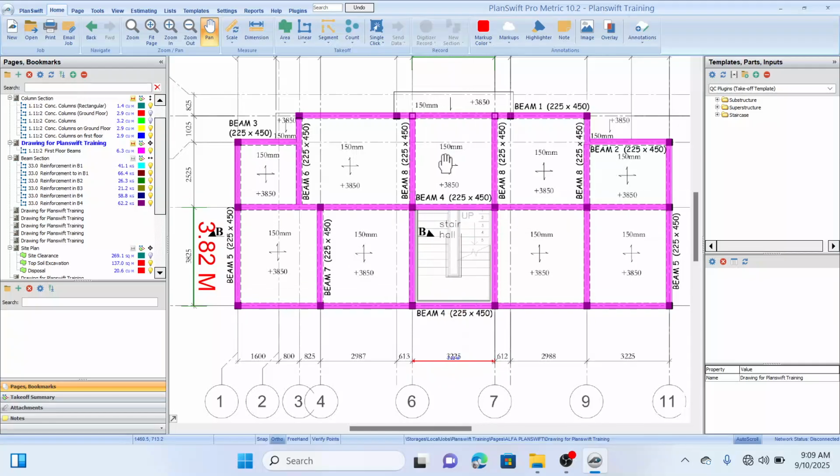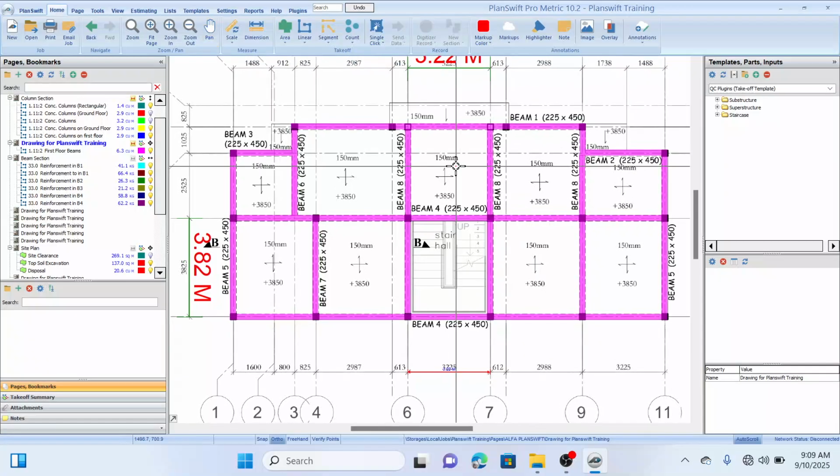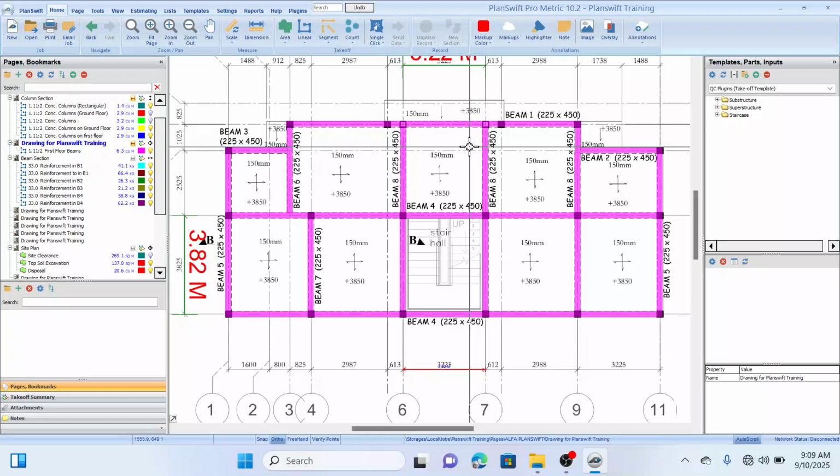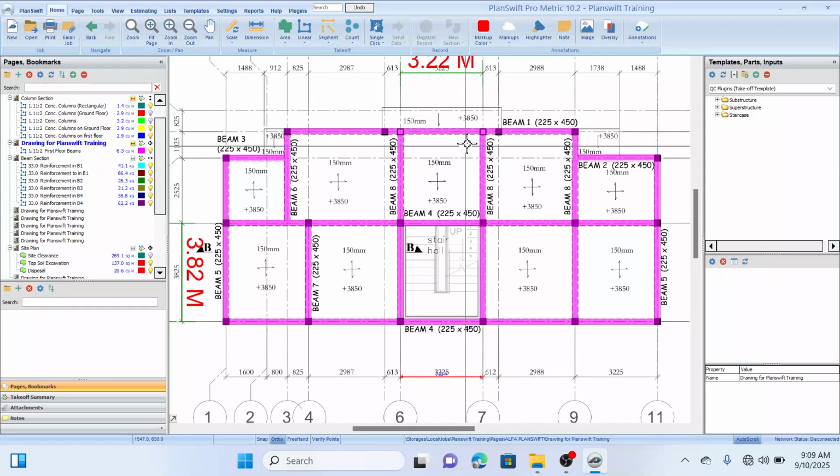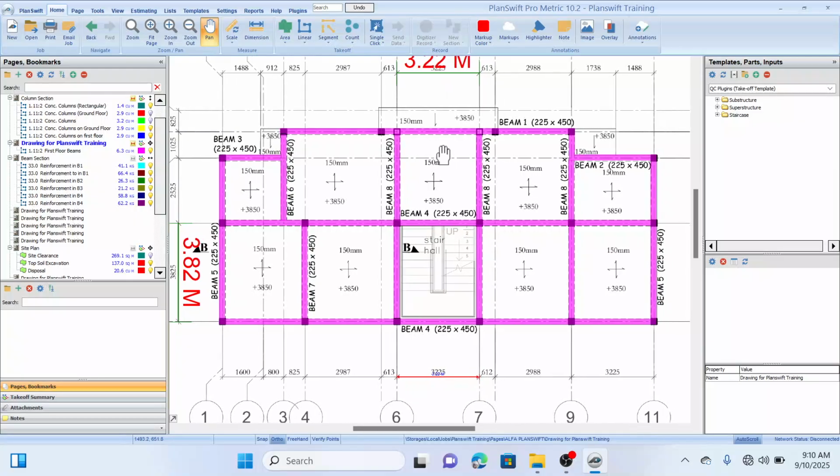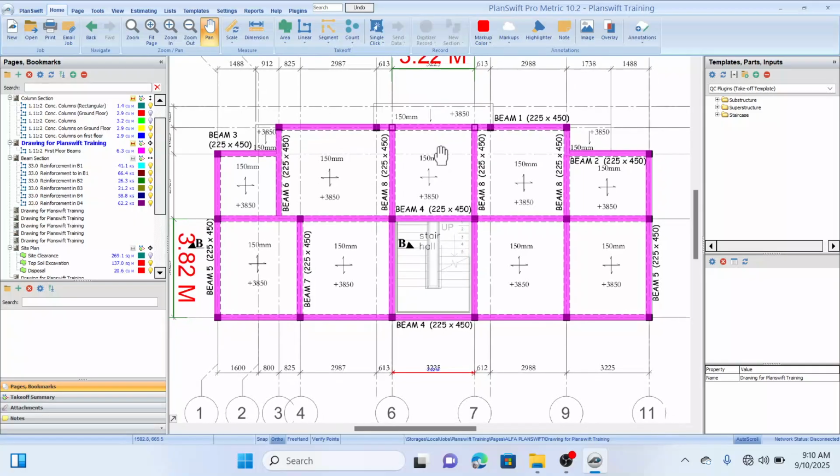We're going to measure our concrete in slab with the aid of our slab plugin, concrete in slab plugin. You can also measure this using your area tool, but you will not be able to measure other items like formwork. If you use the plugin, it's going to be easy. You're just going to measure once, and you have your listing measured alongside your formwork and your concrete work. So let's activate our slab plugin.